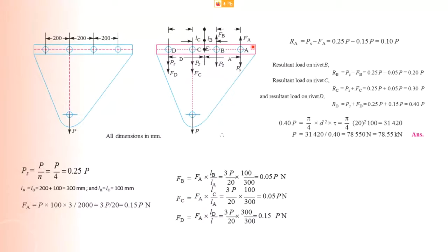So you have your primary shear load PS, PS, and PS based on the applied load P. Each of these shares the same amount. So you take P divided by 4. That means it's 0.25 P for each. And then the eccentricity is somewhere around here.